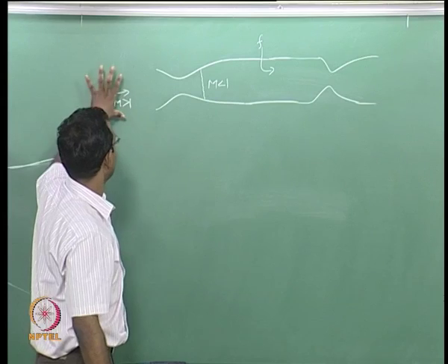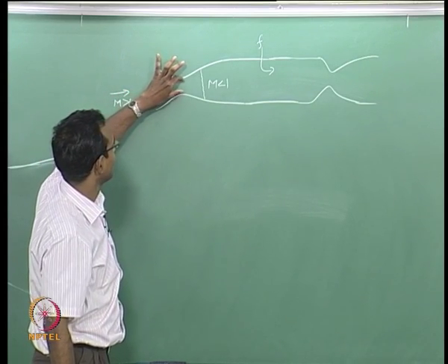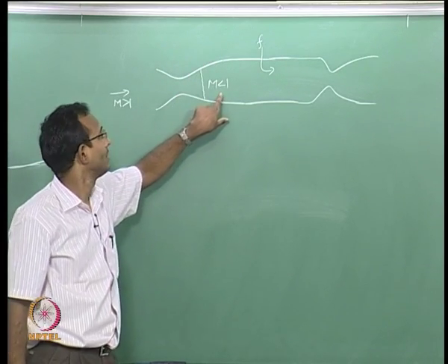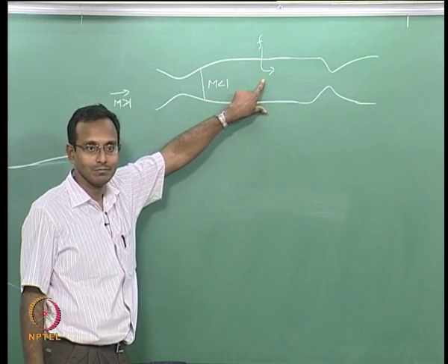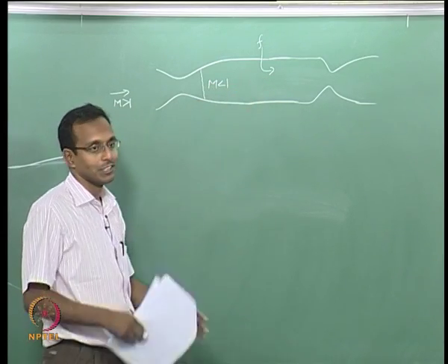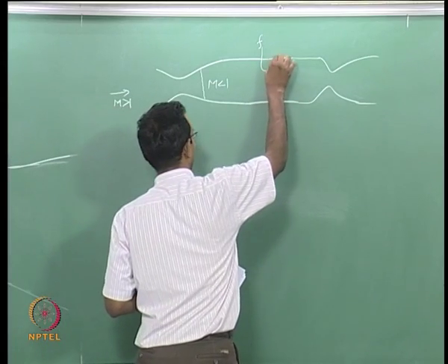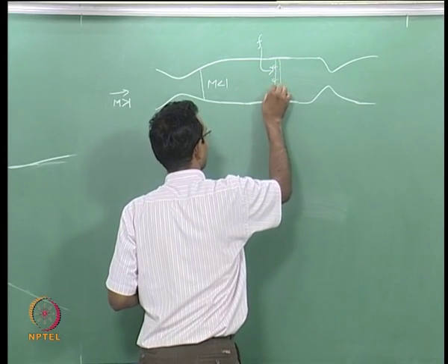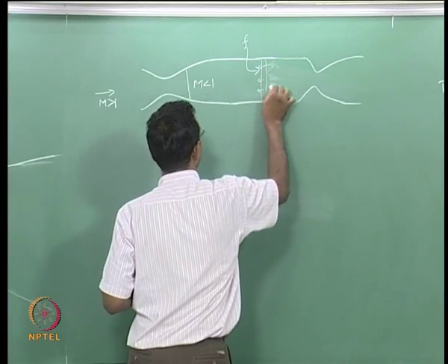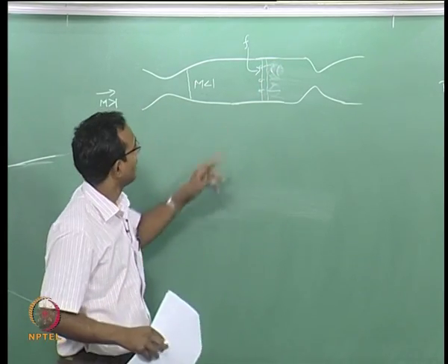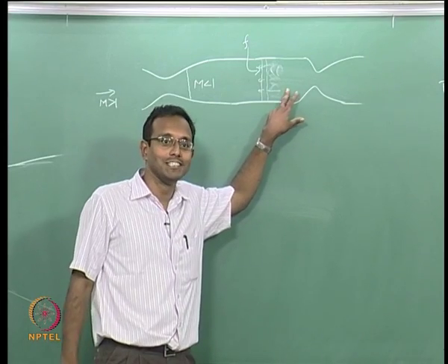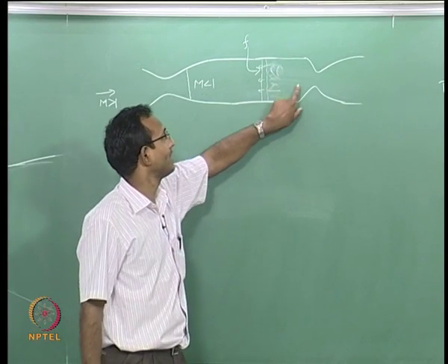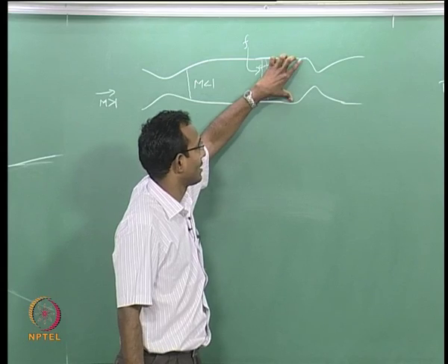Shock is sitting here, m is greater than 1, it jumps across to this condition, and then from here I added fuel, I am having subsonic condition. Of course, now I have to think about similar things, I need some flame holder and injector, etc. There is going to be fuel added to the system and there is supposed to be a flame holder and there will be burning in here. After the burning, now it is subsonic, so it is a little easier, flow is going slow, combustion can happen within this length. And after that, the hot gases are supposed to be expanded.